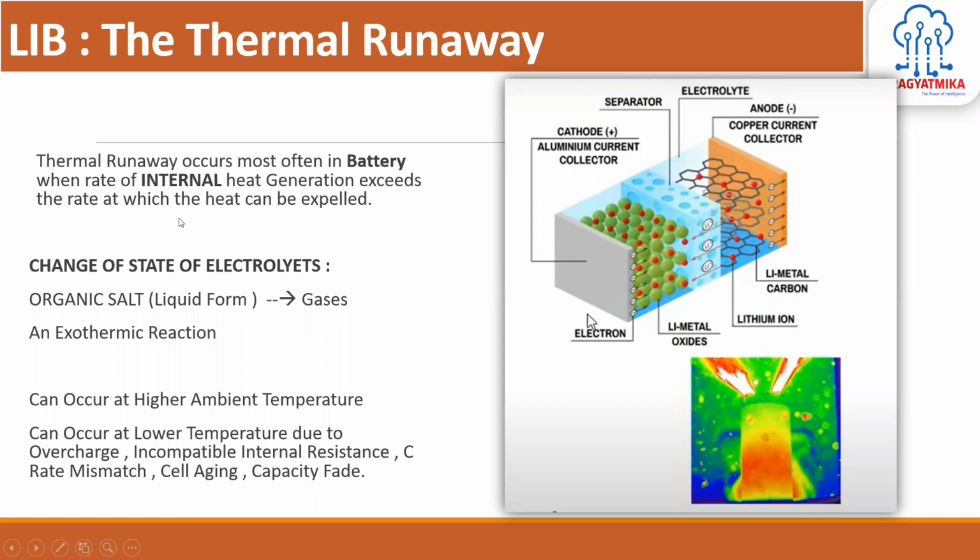So why is it happening? Because the organic salts are there in the form of the electrolyte, and whenever the reaction is happening, gases are emitting out. This is normally an exothermic reaction, but whether or not it is related to the temperature conditions, this can happen at lower temperatures also, and thermal runaway can happen at higher ambient temperatures also.